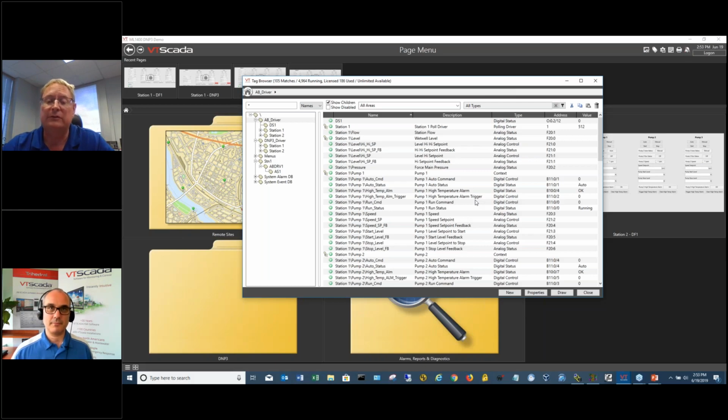I've shown you the show comms and show stats widgets. Those are very valuable in troubleshooting any sort of error, especially the show stats. If you look at the tag database in the tag browser, and your driver tag has a value other than 0, 0 means no error. If it has a value something other than 0, then you can look. If you open up that widget, it'll show you the error message,